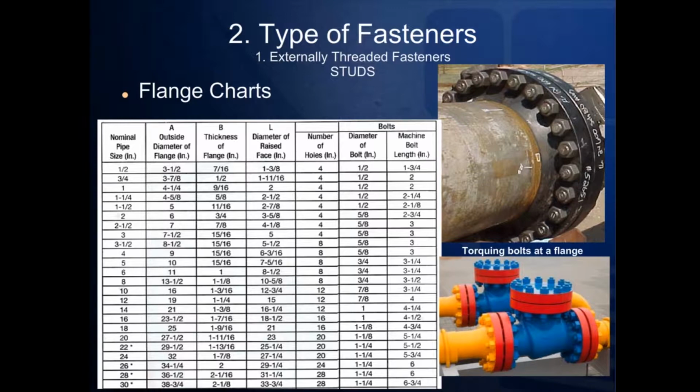To make things easier for pipe fitters, flange charts exist to quickly determine the size and quantity of fasteners needed to assemble a flange. For example, if you're assembling a 150-pound, 12-inch flange, you would use 12 pieces of a 7/8x4 stud and 24 nuts. Just be aware that sometimes items can interfere with your results, like the shape of the flange, the thickness of the gasket, and whether the chart is indicating stud lengths measured first thread to first thread or an overall length.